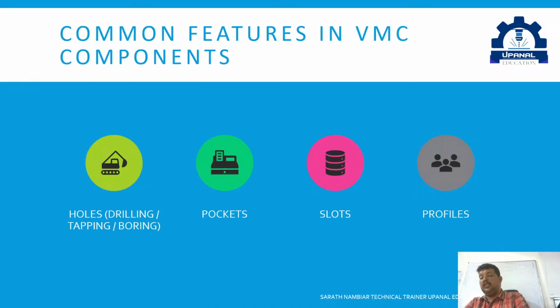Now let us slowly shift our focus back to VMC parts. In turning, the features are simpler, but in VMC, it becomes interesting. You see different types of features. The most common ones: holes, pockets, slots, or profiles. Almost every VMC component you see will have a combination of these. Now, don't worry about machining right now. Just focus on identifying. When you look at a drawing, your brain should start to question, okay, this is a hole, this is a pocket, this is a...